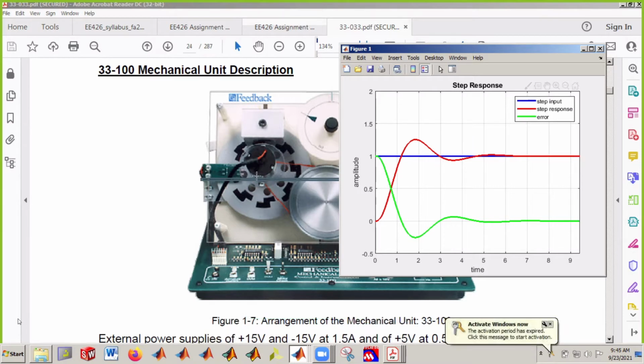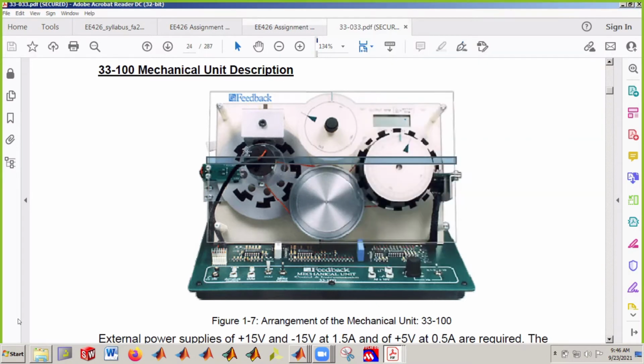Now, because this is a physical system that has inertia, you will see this kind of response for this particular gain. You can see eventually it turns the other way slowly. At this point, it goes from turning counterclockwise to again spinning clockwise, and then eventually dies down. When it reaches the position, you will see this motor completely still. It will not be turning anymore because we are just trying to reach a specific position, and when we do reach it, we want to stay there.